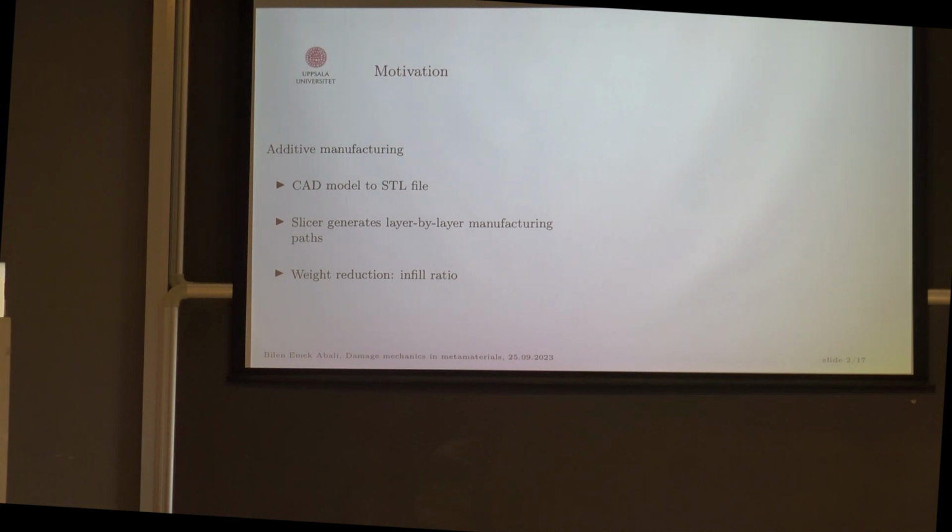It doesn't matter if you use stereolithography, fused deposition modeling, or even a metal-based system, you always use an STL file, which is then used in a slicer to generate layer by layer manufacturing. If it's a powder-based system, a laser is moving, or if it's an extrusion-based system, a nozzle is moving. Something is moving and putting material in different lines or different microstructure.